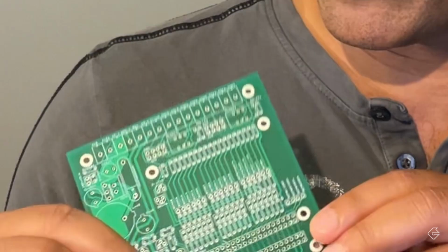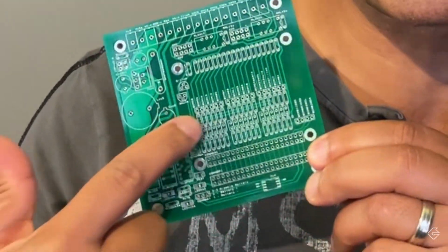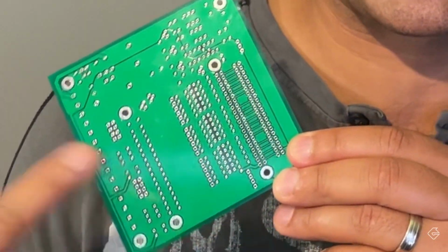When I first discovered that you can do this thing called a copper pour, that's what they call it in this particular PCB design software, your design software may call it something different. It makes wiring the PCB way easier. If you look on any modern board, including some of the designs that I've done in the past, on the top of the PCB you can see most of it is dark green, meaning there's no traces. Wherever you see light green is where you have the copper traces. On the other side of the board, or the bottom of the board, most of it is light green. I made use of this copper pour or a ground plane on this particular board.